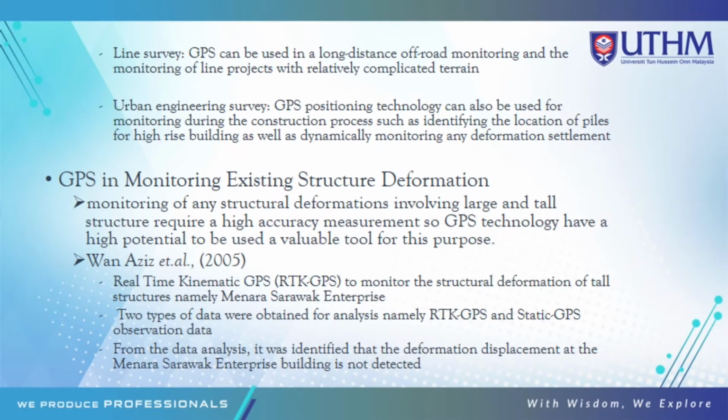Okay, then we move to GPS in monitoring existing structural deformation. Monitoring of any structure deformation involving large and tall structures requires high accuracy measurement. So GPS technology has a high potential to be used as a valuable tool for this purpose. A study by Wan Aziz used real-time kinematic GPS or RTK GPS to monitor the structural deformation of a tall structure, namely Menara Sarawak Enterprise. In the study, two types of data were obtained for analysis, namely RTK GPS and static GPS observation data. And from the data analysis, it was identified that deformation displacement at the Menara Sarawak Enterprise building is not detected.